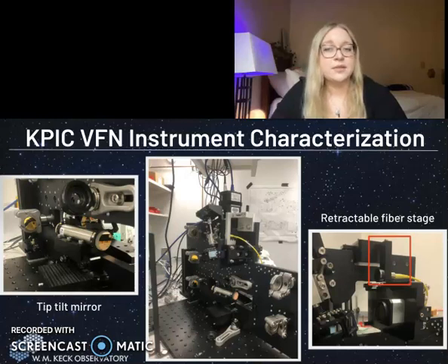And the tests I performed on this stage were to move the stage in and out of the system and see the relative motion in the X and Y direction with respect to the original image. The second test on this was to physically remove the optical fiber and replace it, which will tell us if and how the focus is changing each time it is removed.